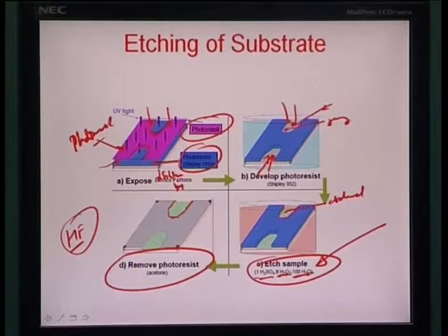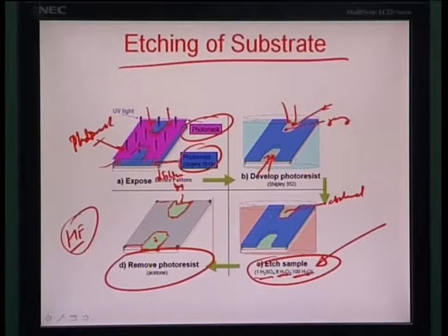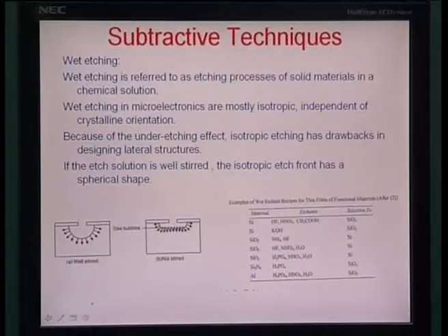Then you can remove the photoresist, so that the original wafer is left with two etches on both ends. These are relatively lower etch depths, on both sides. This can be like etched structures or features within the micron surface. So, this is how etching is done with a sacrificial layer of resist.